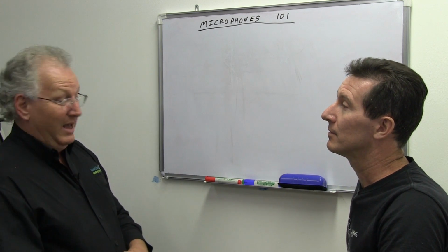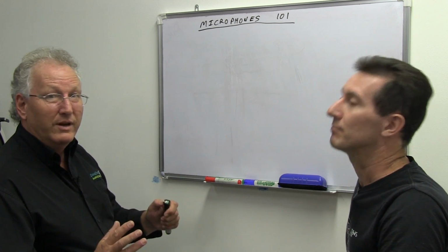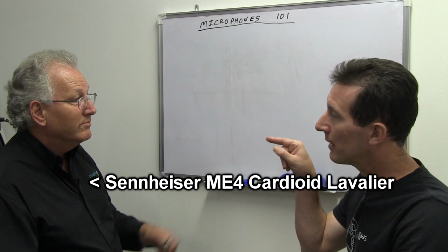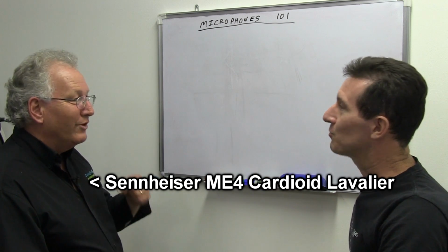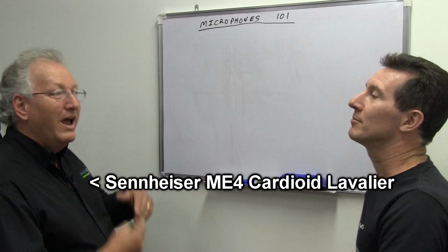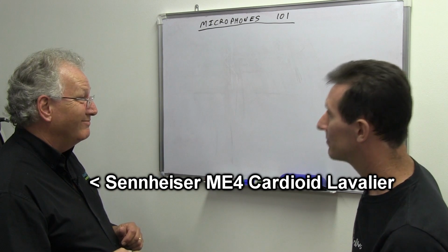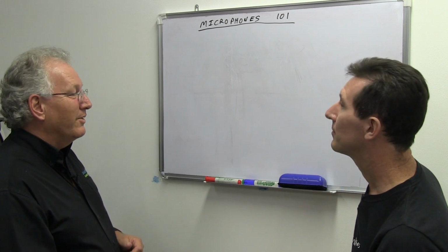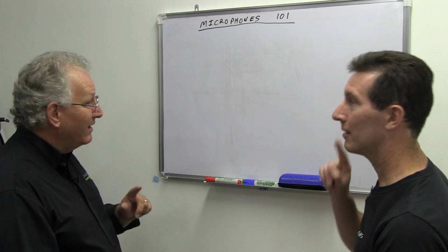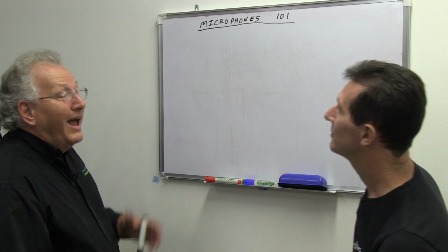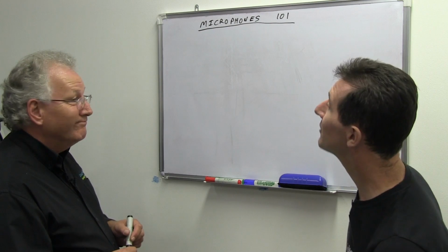We're going to come to operation of Electret microphones shortly. But let's just have a look at the wobbly diaphragm and the acoustics involved, and how we get different pickup patterns. Your one is an Electret condenser, because you don't have enough power to support an external polarising voltage of 60 volts, 90 volts, 200 volts, whatever it takes. So it's assuredly going to be an Electret condenser, as opposed to an externally polarised condenser. But it is a cardioid pattern, I believe. That may quite conceivably be so. Even in such a small size, they can get a cardioid pattern. We'll get into that.